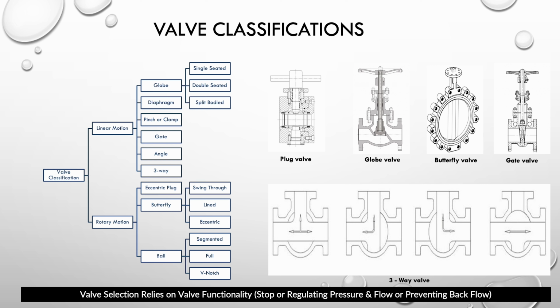The butterfly valve, most likely you're going to see on a cooling water system. In a cooling water system, you want to minimize the pressure drop and you always need that flow. You're not regulating anything in a cooling water system. The best thing about the butterfly is that it can deal with a gigantic flow, doesn't deal with much erosion, and at the same time has the minimum pressure drop across it.